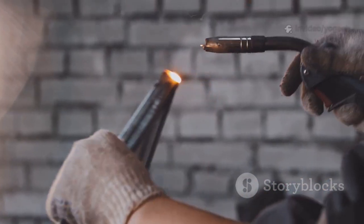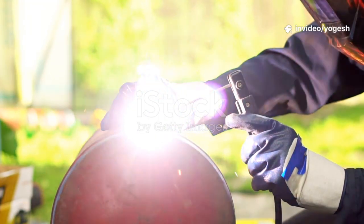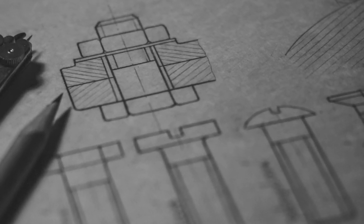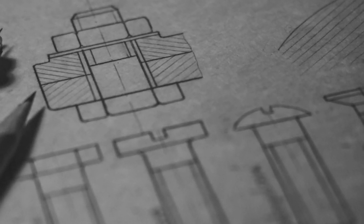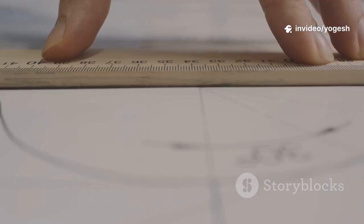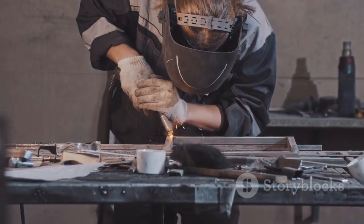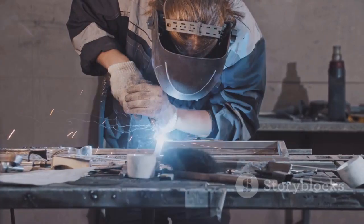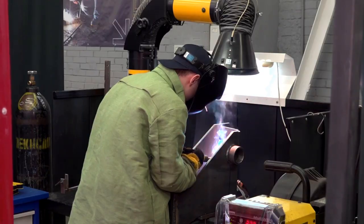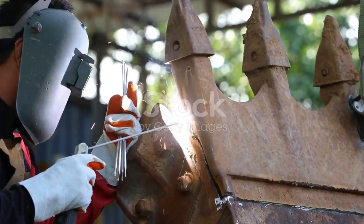Avoid redundant notes. Specify weld sizes appropriate for the application. Oversized welds waste material and cause distortion. Maintain consistency in symbol size and style throughout your drawings. Keep symbols clear of dimension lines and notes for readability. Add detail views for complex joints when needed. Stay updated with the latest AWS and ISO standards. Precision and ongoing learning are key to effective, reliable weldment design. Master the language of welding symbols and your designs will be built strong and safe.